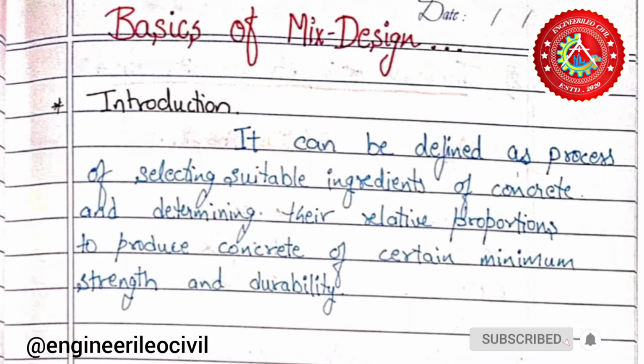Strength of concrete varies as an inverse of water cement ratio. After mixing and proportioning, the resulting concrete should have the following properties. It should possess maximum density so that it will be strongest and watertight. Fresh concrete should have enough workability so that it can be placed in formwork easily and economically. The cost of materials and labor required to form concrete should be minimum.